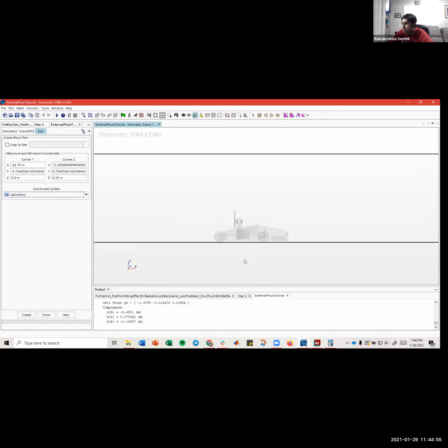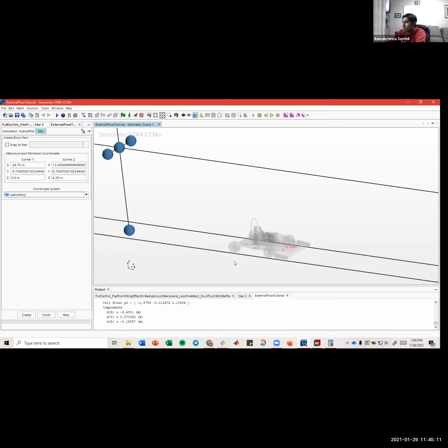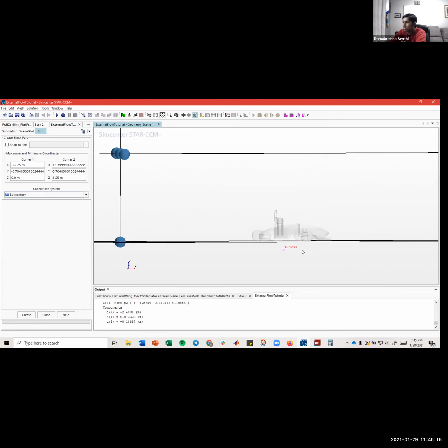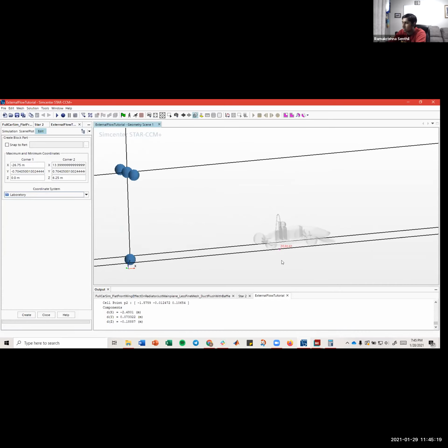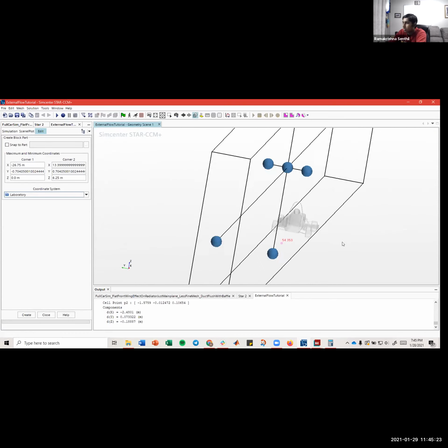One other thing to note is that the bottom part of the wind tunnel needs to intersect slightly with our wheels. The reason for this is that we're going to simulate the wheels to be a rotating medium. So we want the wind tunnel to be intersected a little bit so that there are no complications in the CFD calculation.